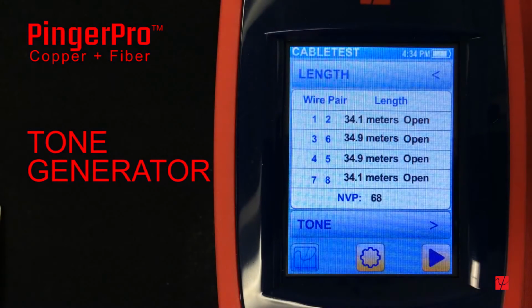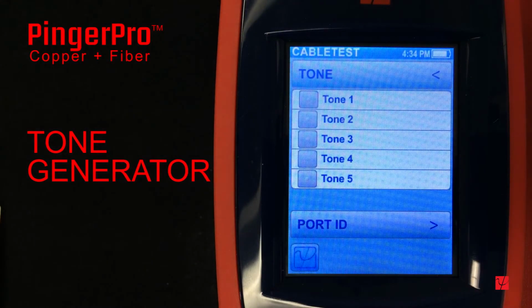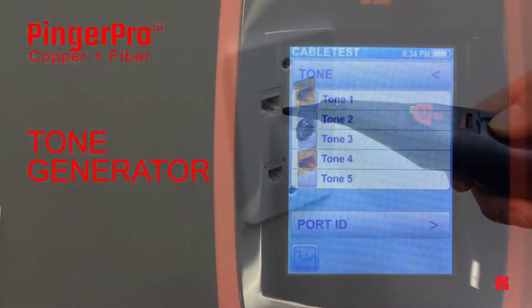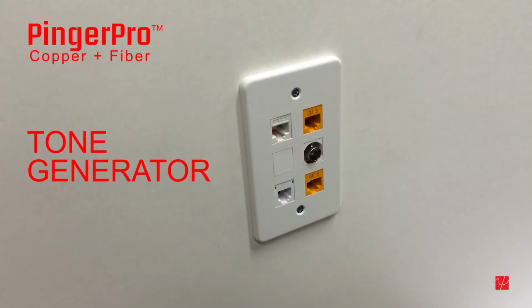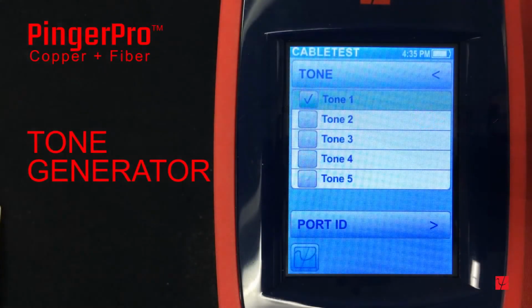Pressing the tone button will bring up the tone generator. The tone generator sends a signal down a cable that can be detected using a Psiber cable tracker probe that is available as an option. Connect a cable end to the PingerPro. Select one of the tones and hold the cable tracker probe to the connected outlet or a cable and you will hear the tone. This function is used to trace the path of a cable to locate a fault or identify a specific cable, outlet, or punchdown that would otherwise be difficult to identify.